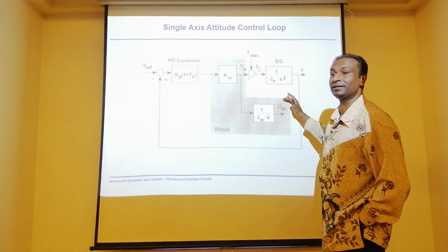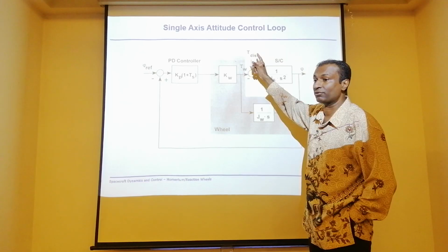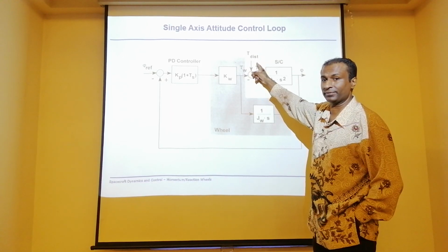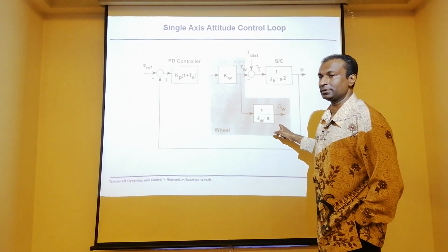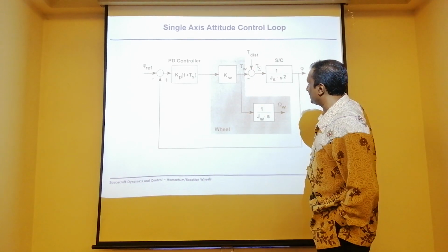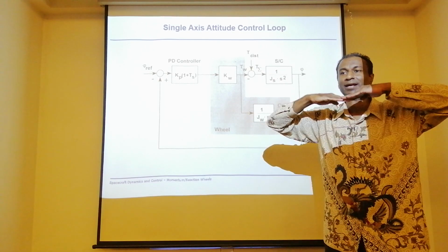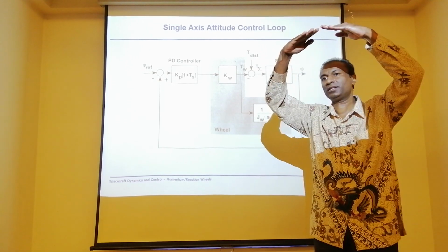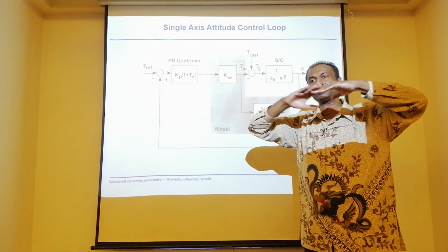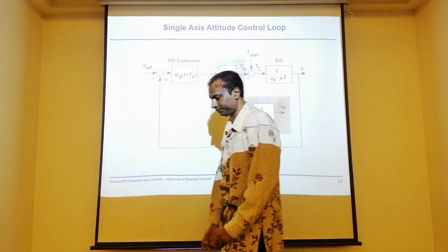Adding means what I'm saying, you have to add a negative torque here for this to brake. You add torque here, it cannot respond. If you have a positive torque and this is accelerating, you keep on giving positive torque, this is going to go stagnant at maybe 5000 RPM, cannot go further. Then the satellite becomes uncontrollable. Okay? Go on.